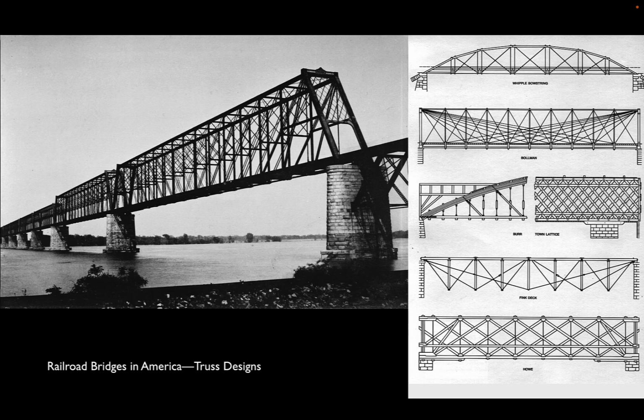And you can see that what that does is it fixes all the points of the truss into space. It means that the truss can't deflect because triangles don't change their shape. And that means that the load on the deck has to go into all the members of the truss. And you can do some very simple calculations to figure out how loads will flow through that network of triangulated